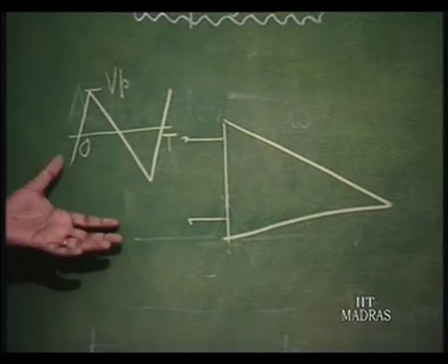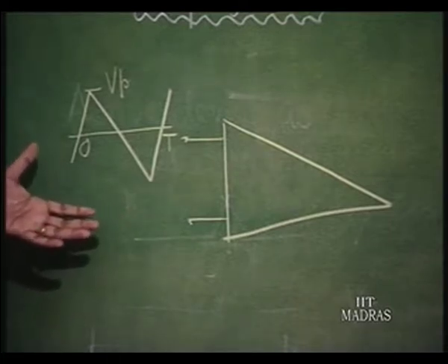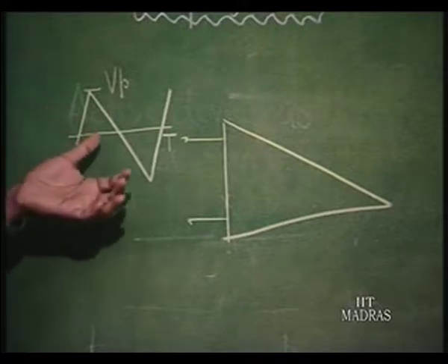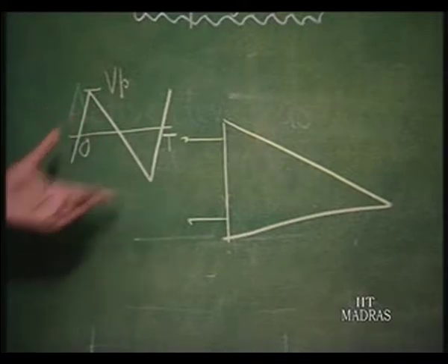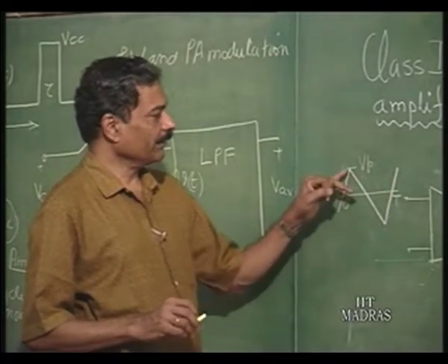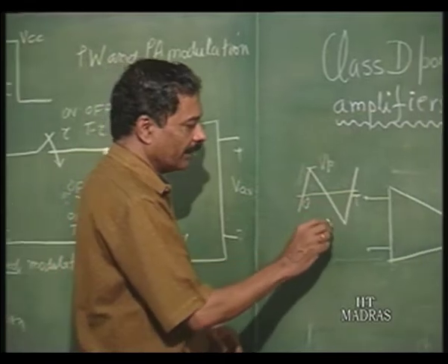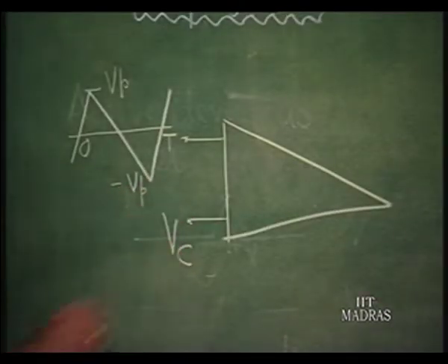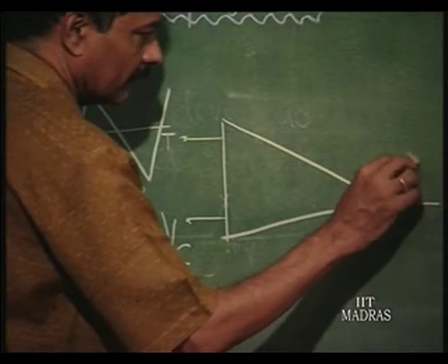Say if you have a clock with this kind of period, a square waveform with this kind of period, you can convert it into a triangular waveform by integrating. So, let us say that sort of waveform has a peak value of Vp and time period of t, and we put a voltage for comparison, we call this Vc, and let us observe this output here